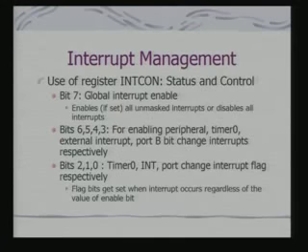They are timer overflow interrupts, USART interrupts. When there is a character waiting in the buffer to be read, there can be an interrupt. AD conversion interrupts: when analog to digital conversion is complete, there can be an interrupt. The LCD interface module can generate interrupts, and there are others also, because as we increase the number of peripherals on chips, we need a mechanism to control those peripherals, and they can also be a source of interrupt for the PIC processor. And these interrupts are managed by use of a few registers.